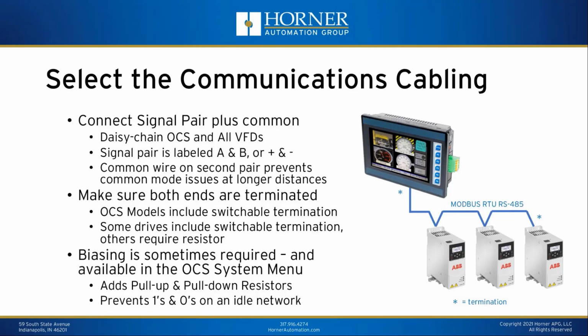Now, you're going to daisy chain all the components on the network. So if it's just an OCS and one drive, it's basically the equivalent of point-to-point wiring. If you have multiple drives, for instance, you're going to be using a daisy chain approach like in the diagram.